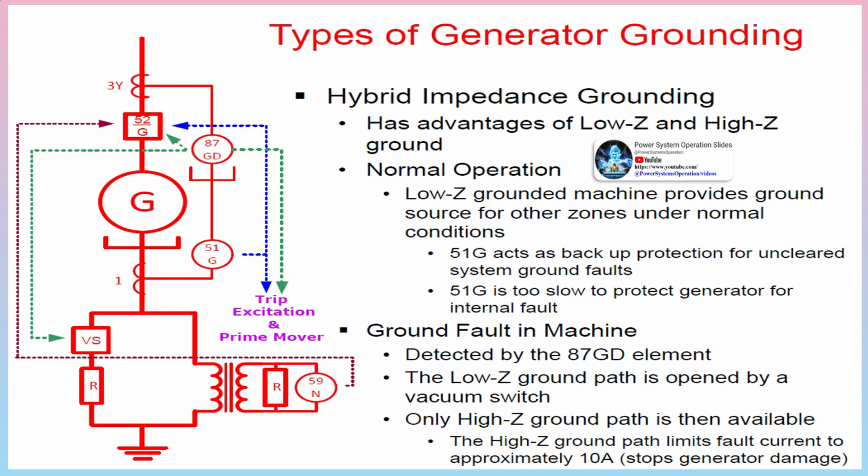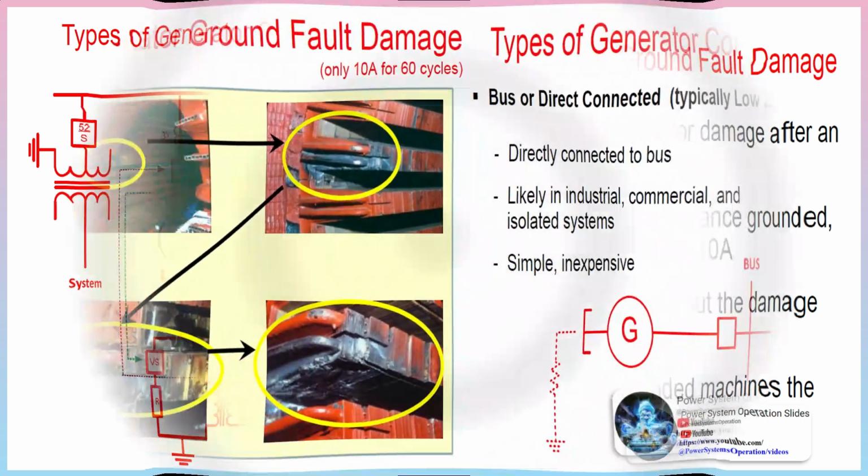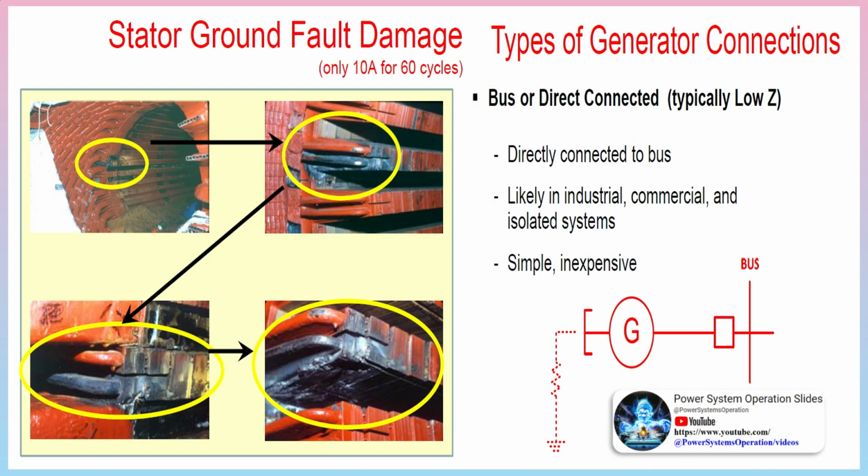Protection against insulation failure. The main protection provided in the stator winding against phase-to-phase or phase-to-earth fault is longitudinal differential protection of the generator. The second most important protection scheme for stator winding is interturn fault protection. This type of protection was considered unnecessary in previous days because breakdown of insulation between points in the same phase winding, contained in the same slot, and between which a potential difference exists, very rapidly changes into an earth fault, and then it is detected by either the stator differential protection or the stator earth fault protection.